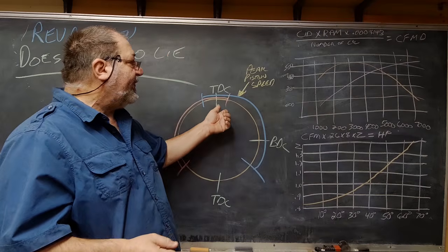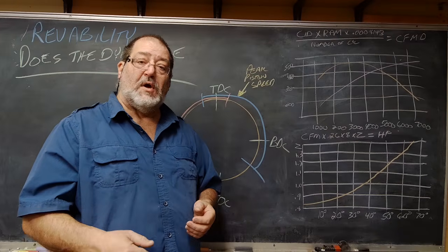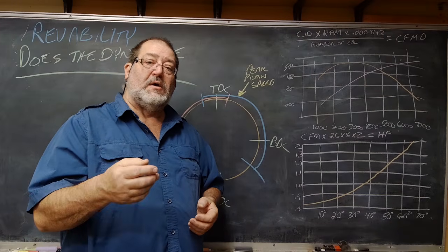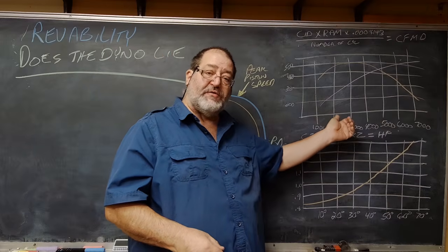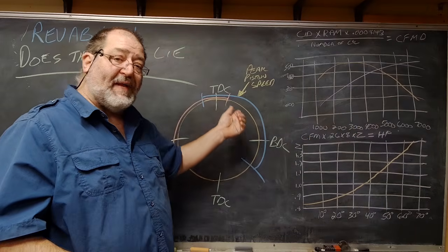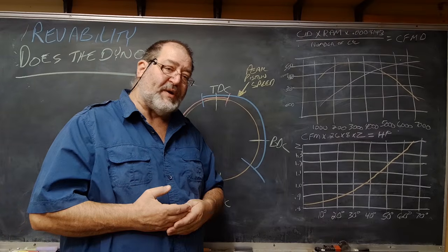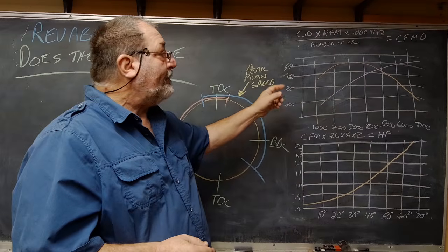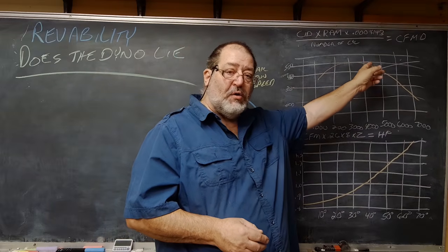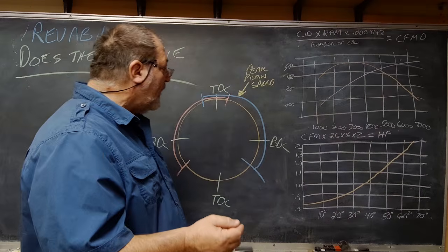You're going to wind up with overlap, but if you're doing one of those engines, you may only need 4,000 to 8,000. And so down here doesn't matter. You don't care about overlap. But the overlap isn't really helping you. It's damaging that power down here. But it may gain you a little bit with a tuned exhaust, which we talked about before.